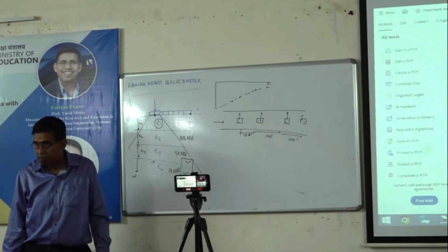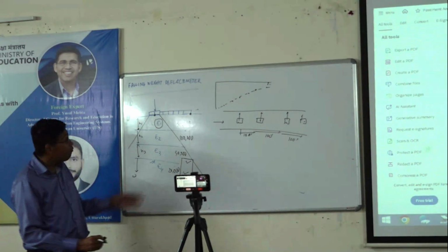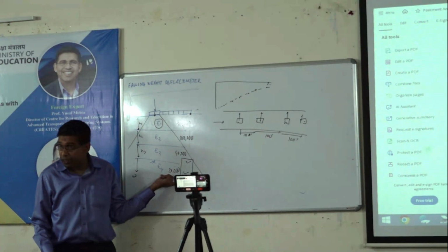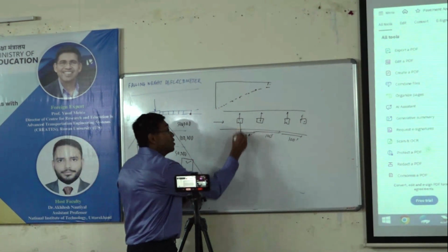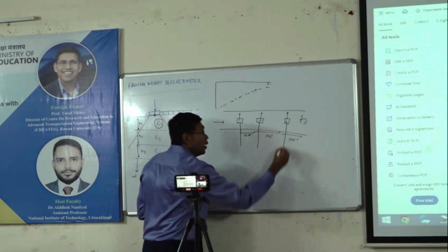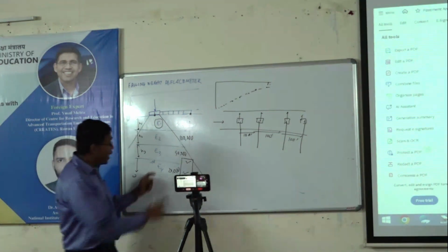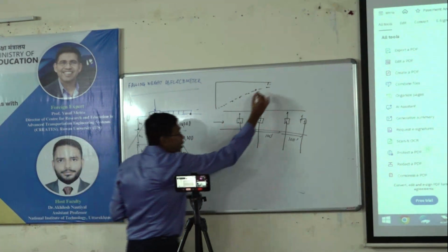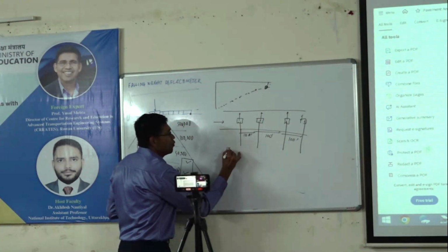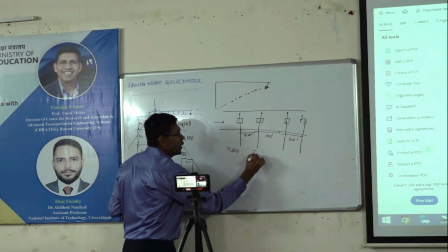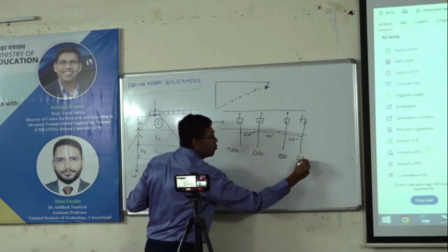What is it? It will not change. What is my chances that within 400 feet my subgrade will change? Negligible, right? So you have to run the analysis here, you have to run the analysis here, you have to run the analysis here and here. And let's say you get the bottom number to fit closest to D7 and you get 15,000, 5,000, 3,000, 22,000. This is E4.